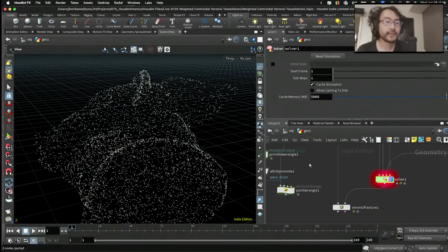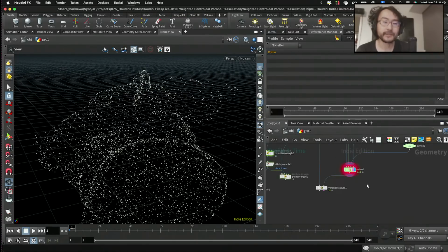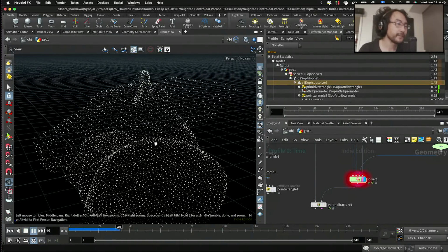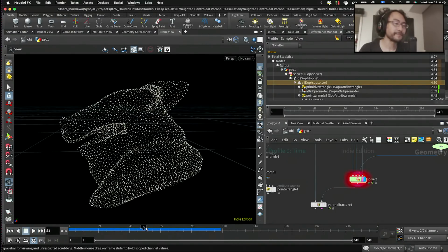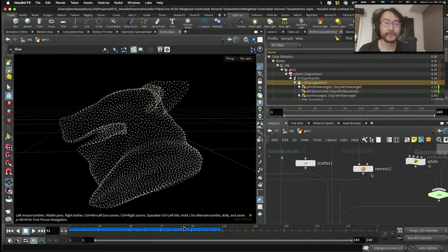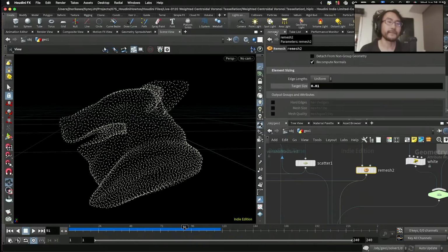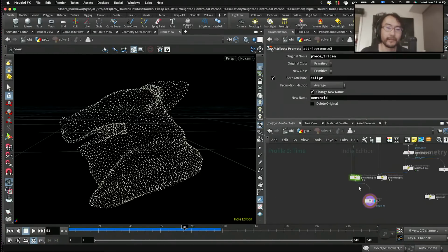The things you want to check is the speed here and the precision. See, if I play it, you can see this is much faster, and the result is not too bad based on the resolution. If you increase the resolution of this mesh, you could further get more precise, or if you make the mesh more rough, you get faster result, less precision. So if you just need a simple animation or a rough result, then I think this is the way to go.